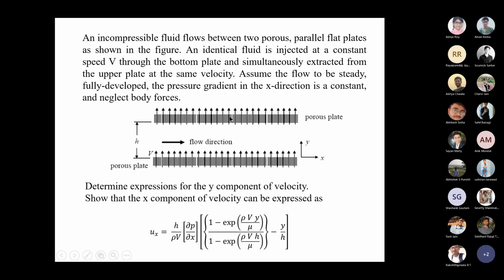There may be two solutes present in the system, and then you choose the membrane in such a way that the molecular weight cutoff is in between the molecular weight of solute 1 and solute 2. So if you have NaCl and a salt of high molecular weight present in the system, and you would like to concentrate that high molecular weight solute, you are going to provide an ultrafiltration membrane or an RO membrane through which the salt can pass, but the larger molecule will not be able to pass.